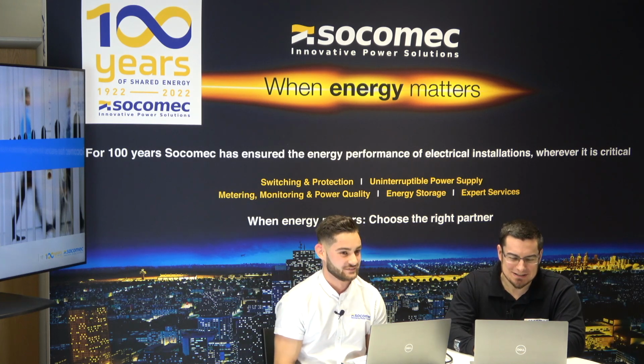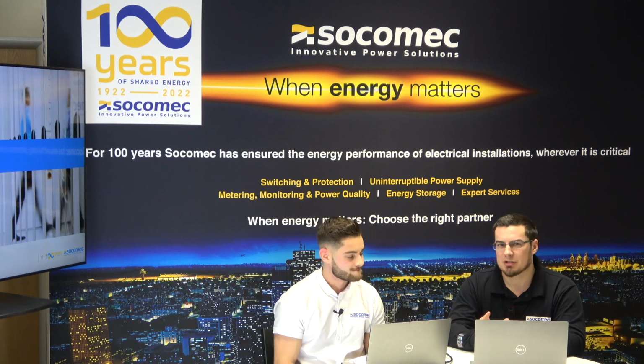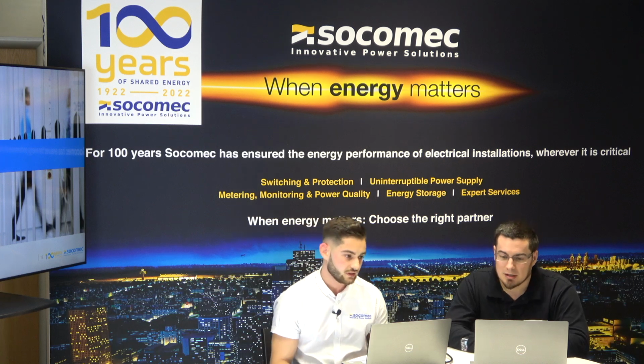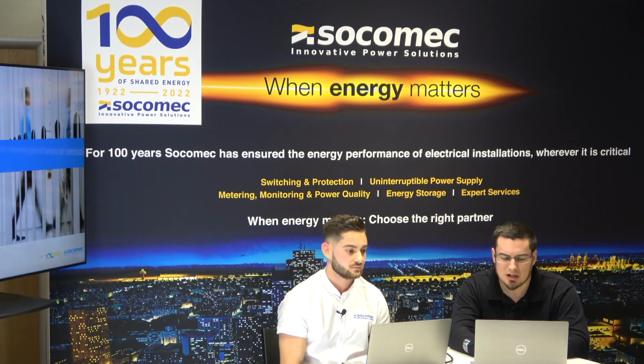Thank you. And this one, if somebody's got a 4-wire, 3-pole version, but they've got no neutral on the incoming, would that work? I think we touched on this very early on, and they are built differently, and the inputs for the power supplies especially, things for the fans and things are all wired slightly differently depending on whether you've got a 3-wire, 4-wire system. So no, initially we would need to know exactly what kind of infrastructure you've got to make sure we've got the right STS for you from the get-go. Nice one. Can you see any other questions? There's a few people sharing it about, but there are none others that have come in.